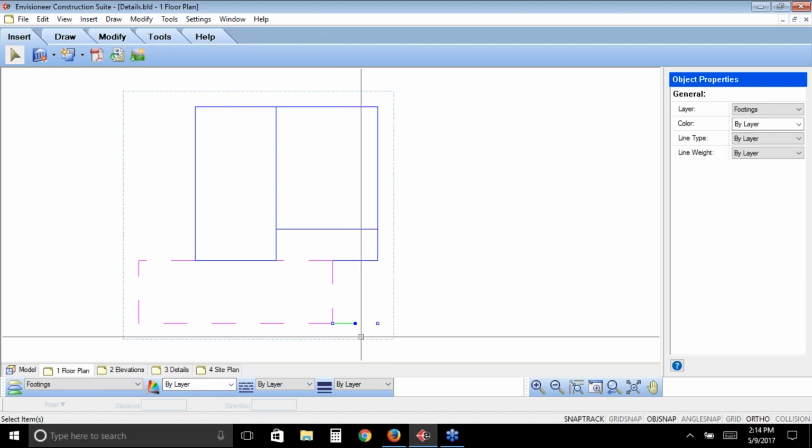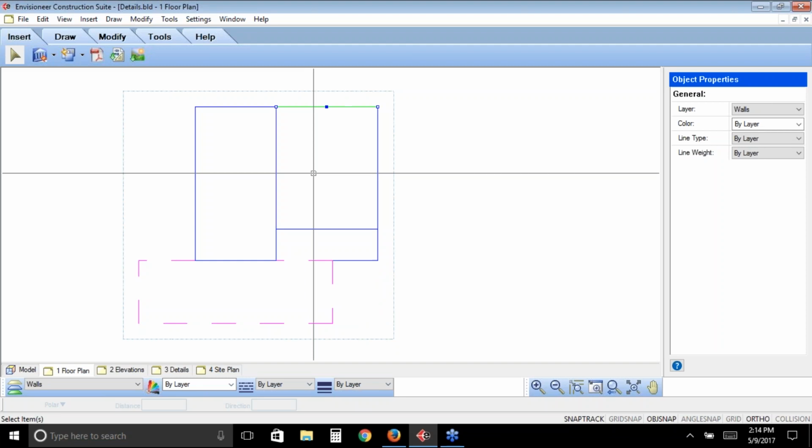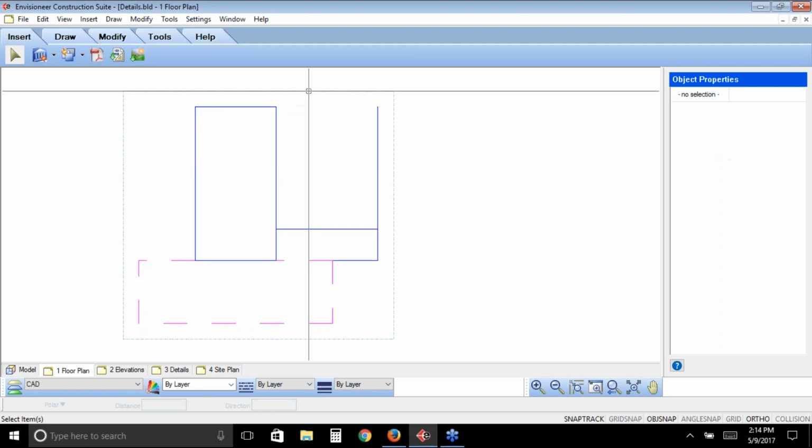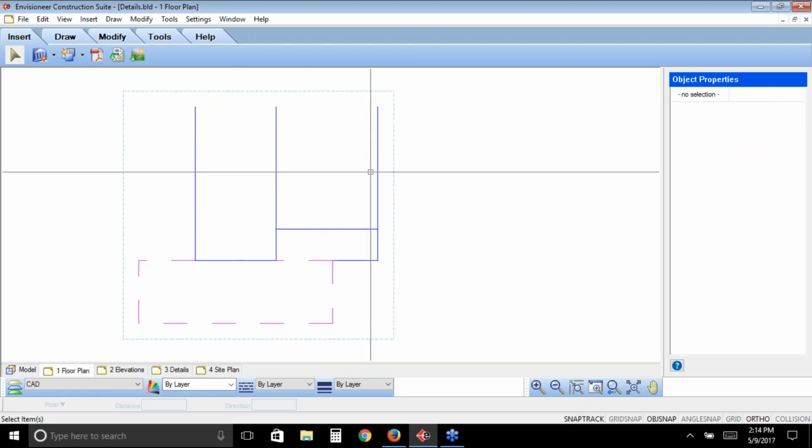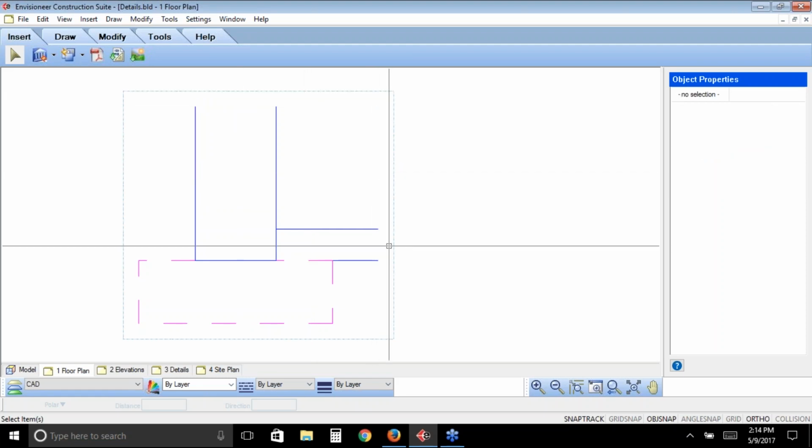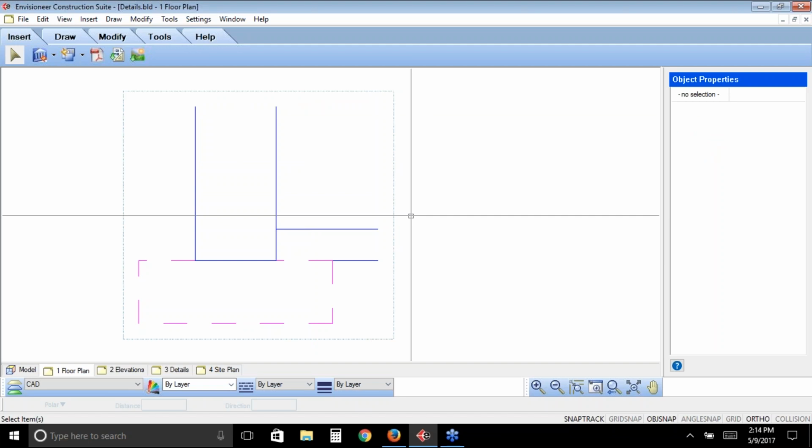And this line right here, again, showing the extra line of the footing because it's running through the entire building, I'm going to delete it out. The lines that cap off the top of our footing and our stem wall, drawn to show where I stopped the actual detail, I'm going to remove those as well, so I get a more simplistic view. Once I'm done editing all the little pieces that I have here, I hit escape.